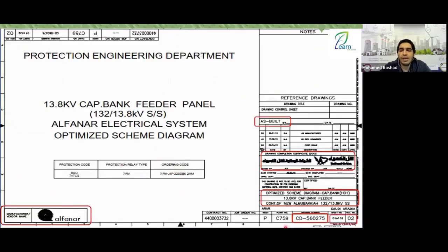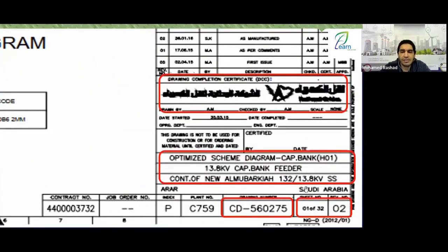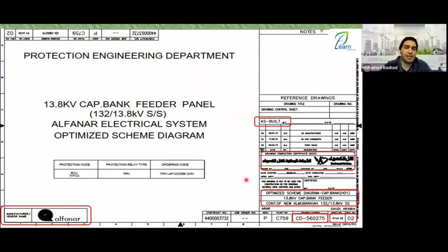Then you have the last part, I mean the sheet number, which is the last part in the drawing, meaning the sheet number, how many pages it has, its revision, this is the complete version. Okay, so here, everything we studied before is data about who the manufacturer is, the vendor, etc. Who is your end client? Is the drawing version pre-commissioning, markup, or as-built? What is your project about? Or what is the description of this cell? What is the drawing number, the sheet number, the page number you are on, and the total number of sheets, everything, and division. All right, great.